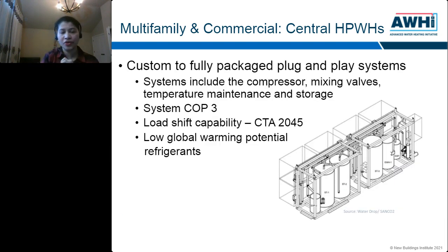So this is where I wanted to go over the emerging technologies which are planned to be packaged or skid mounted. At least 2 manufacturers this year are coming out with this packaged approach, and as part of the Advanced Water Heating Initiative, Ecotope and BPA are working closely with them. The whole approach is that the compressor, the mixing valve, and the storage are going to be factory installed on a skid. So it's much easier for market adoption with such an approach versus the current custom designed approach. The units that are coming out are all going to have load shifting capability, with low global warming potential refrigerants.